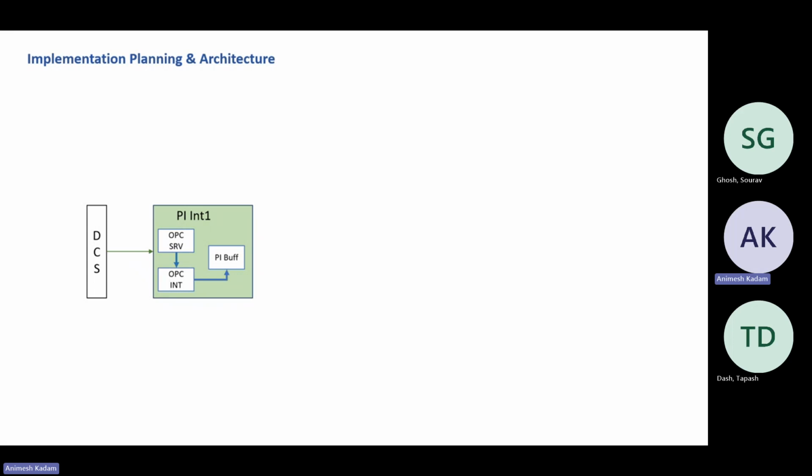But if the OPC server and the interface node are on different systems, in this case you need to do the DCOM configuration or DCOM setting. Are you aware of the DCOM settings? Yeah, a little bit.